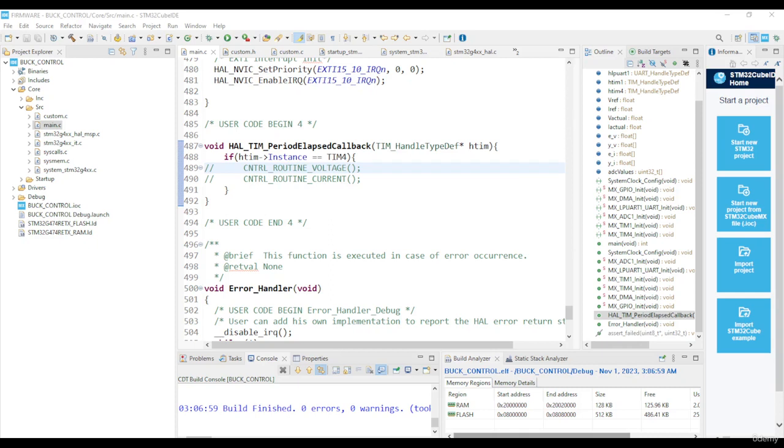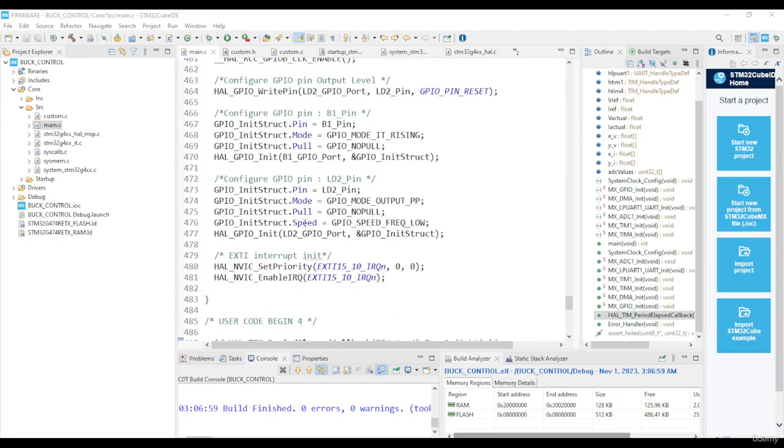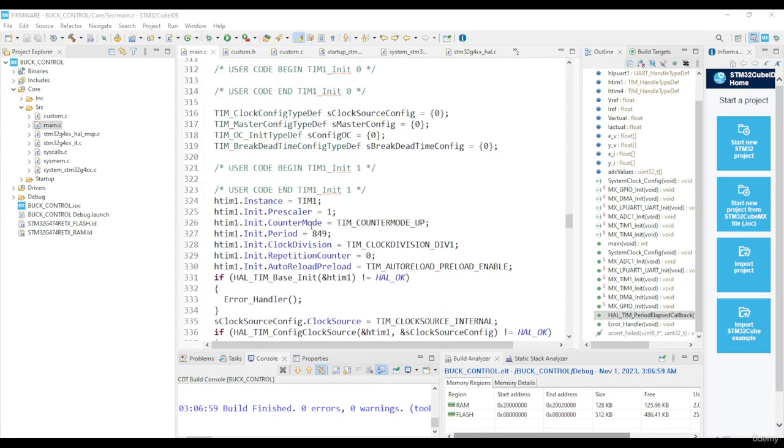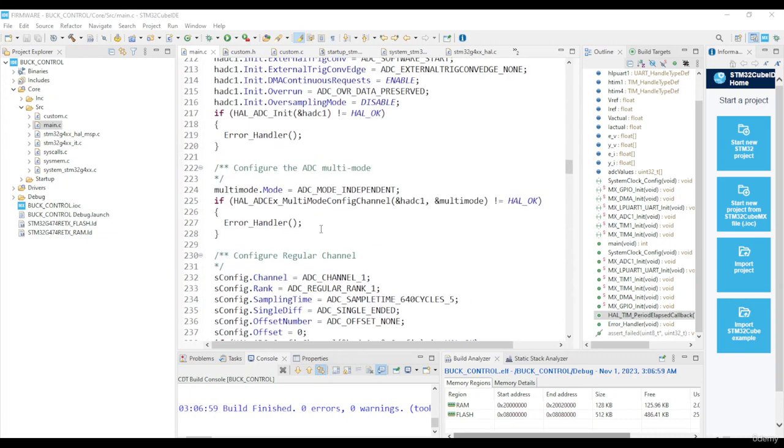Alright, in this section, I'm going to be dealing with average current mode control. Essentially what this means is you're actually controlling the current through the inductor. Instead of controlling either the output voltage or the output current, you're basically controlling the current through the inductor. And what that entails is you have a double loop. It can also be called double loop control. And what you get in double loop control is an outer voltage loop that makes a current reference for the inner current loop.